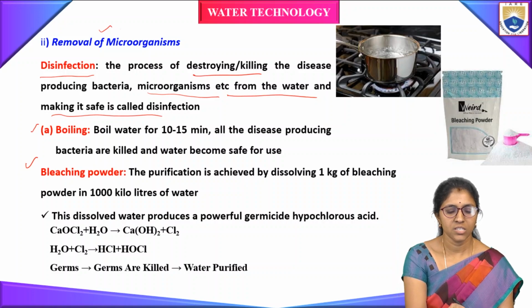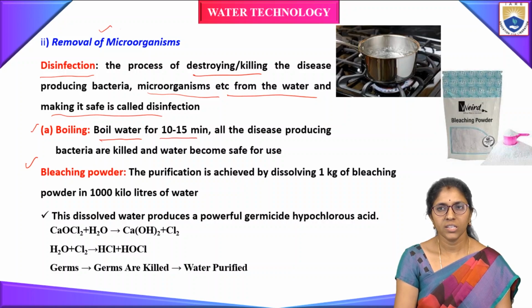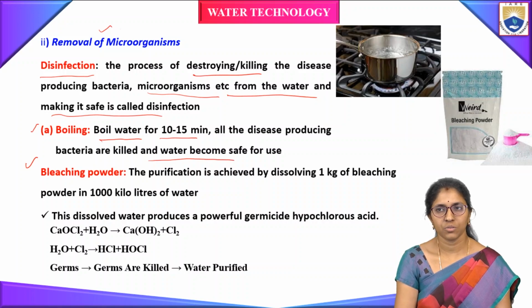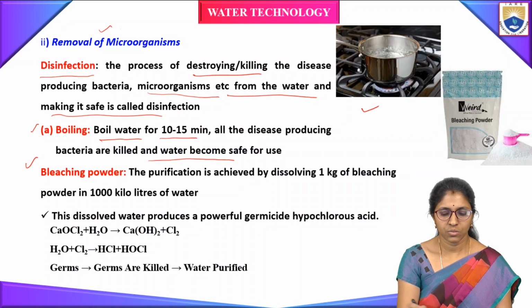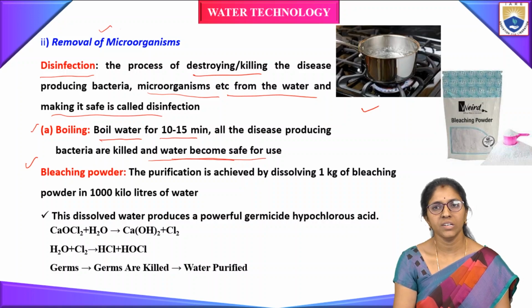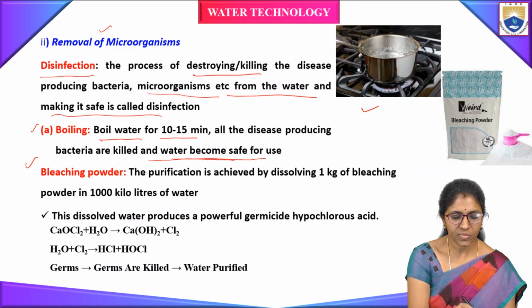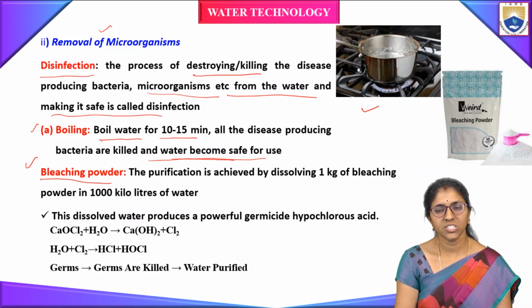First one is boiling. Simple process is boiling. We have to boil the water for 10 to 15 minutes and all the disease producing bacteria are killed and water becomes safe for use. So by boiling water, we can kill the disease producing bacteria. This is the simple and oldest process of disinfecting the water.